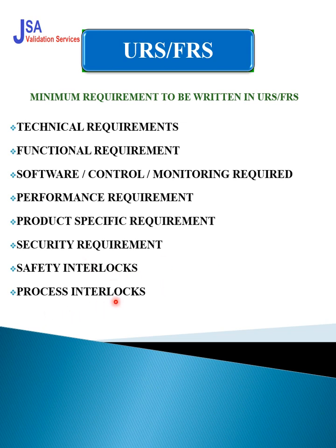Process interlock means if there is an increased amount of humidity or malfunctioning of a dryer or compressed air generation system, and the dew point increases, then it should automatically drain off all the air so that it does not go inside the process area. So that is also a process interlock. If any process interlock is required, then you have to go for the process interlock.